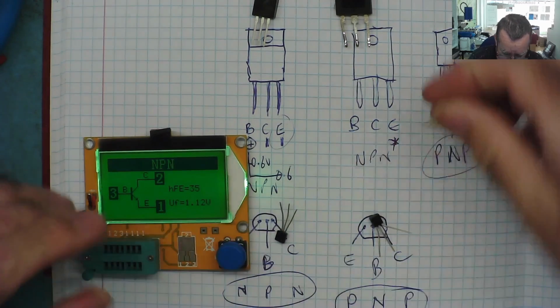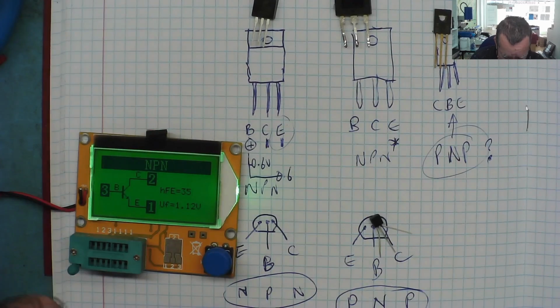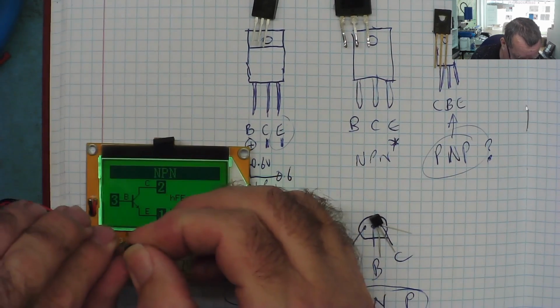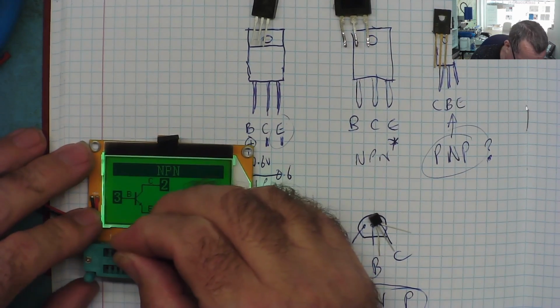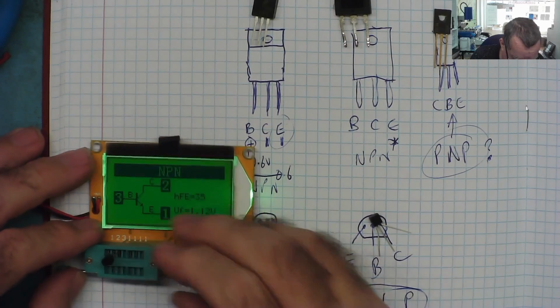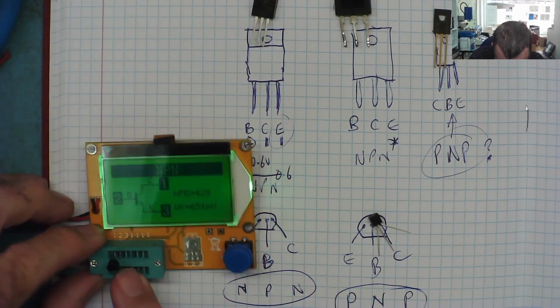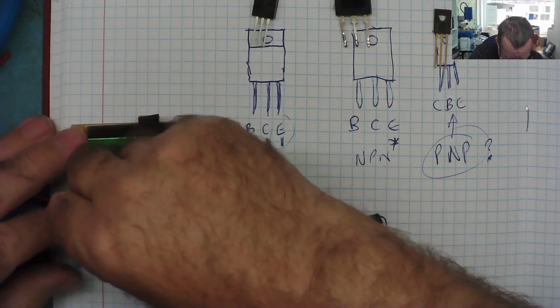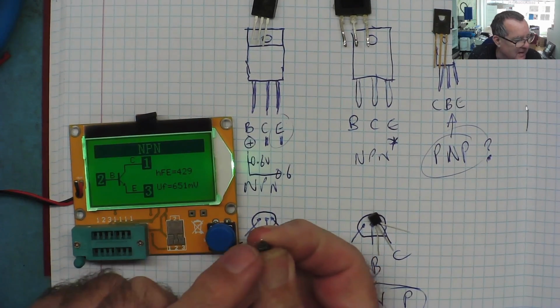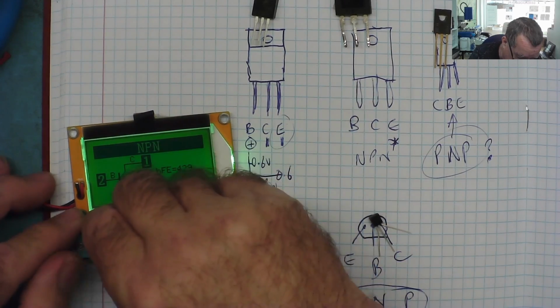Yeah, I have a part number. Right, let's go to this one. So, emitter should be in pin 1, base in pin 2. Okay, so emitter should be pin 1, oh, pin 3, sorry. Let me look at the right way around. Just check. Yes, emitter's this end. So emitter in pin 3, my mistake.